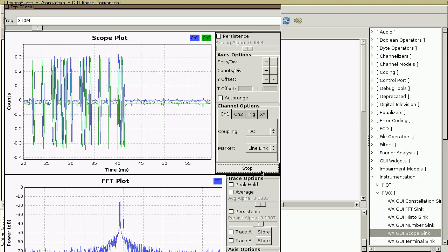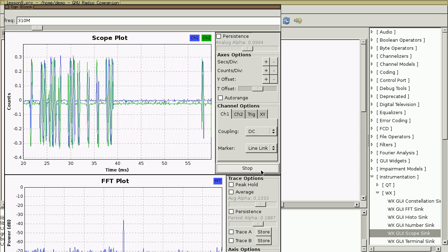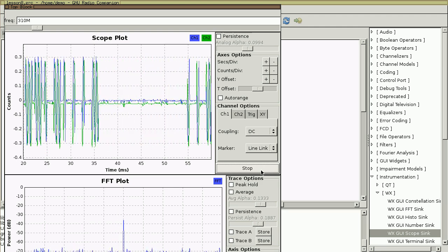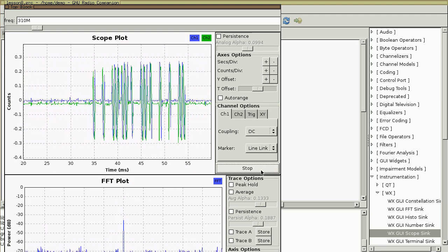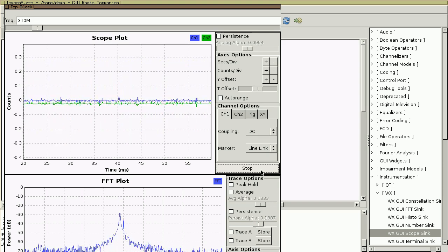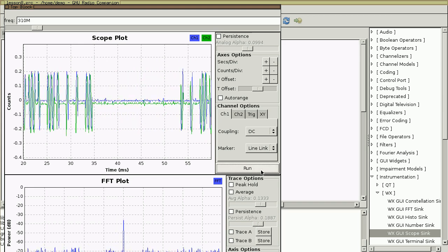This modulation is known as on-off keying. It's the simplest form of amplitude modulation. The amplitude is changing to extremes. The transmission is either on or off, and that's why it's called on-off keying. In many ways, it is similar to Morse code. You can imagine this type of transmission coming from a telegraph key. You could manually hit a telegraph key, short, short, long, short, and so forth. However, a human couldn't do it this fast.